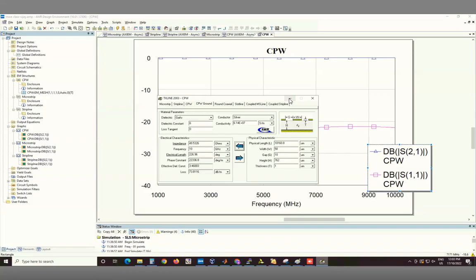What is important for a CPW transmission line? Like something which is not obvious from the design itself, something you have to do. Exactly. The 2 grounds have to be at the same potential.